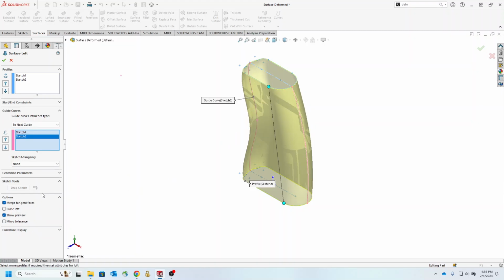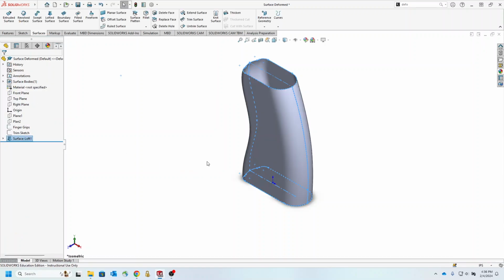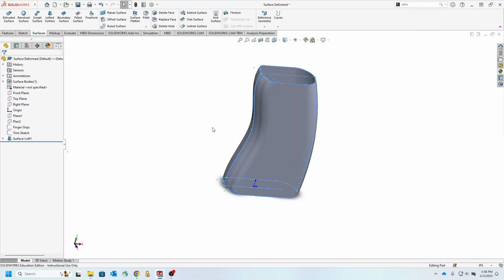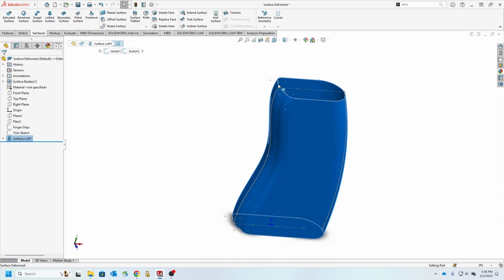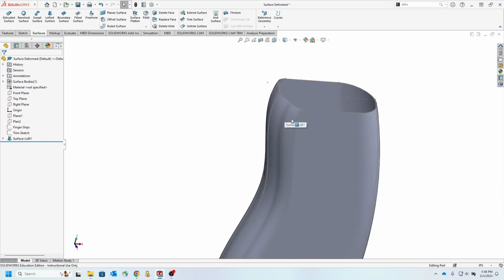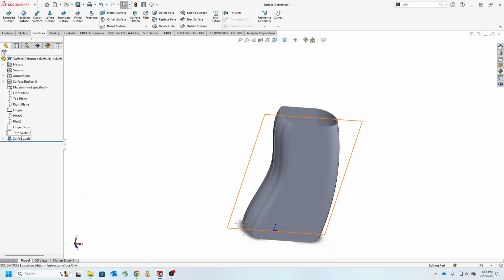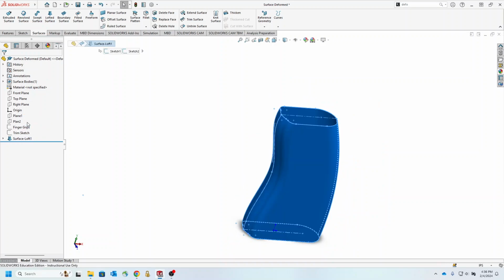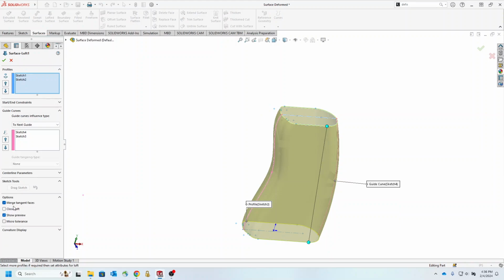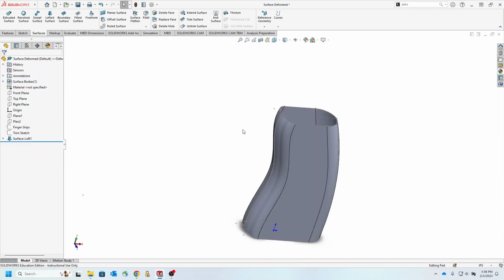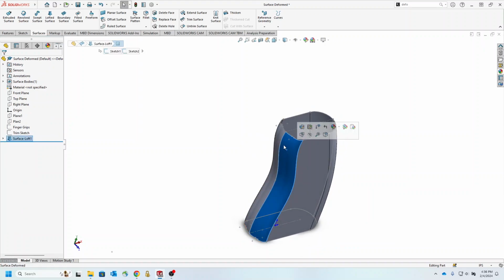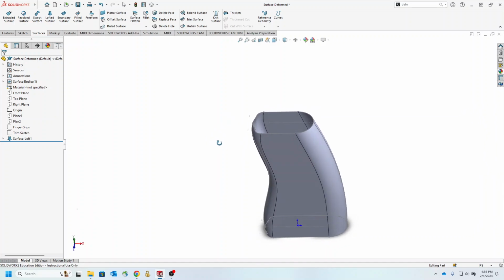And here there is something called tangent faces. Let's see what happens with that. If you click on the tangent faces, there is a smooth and everything is one surface. There's no face here. Everything is one entity. But if you go back and select this option, remove that merge tangent faces, then these faces of this surface are selectable.